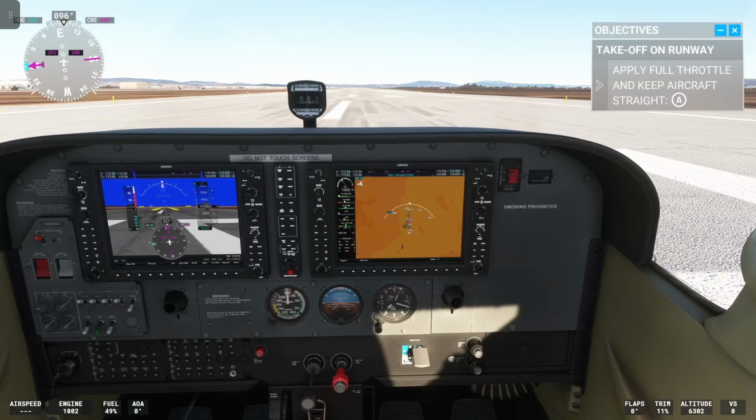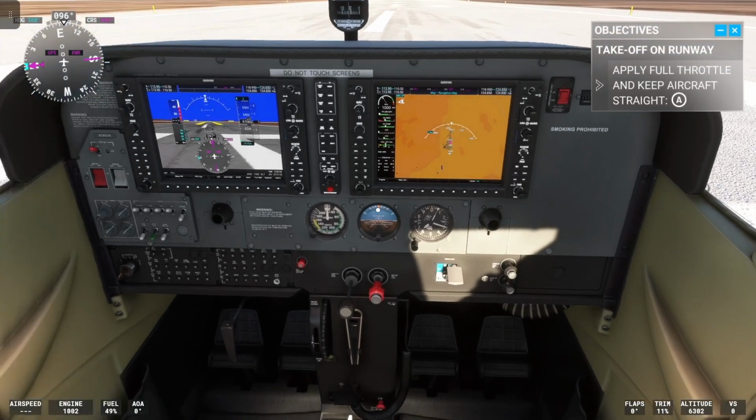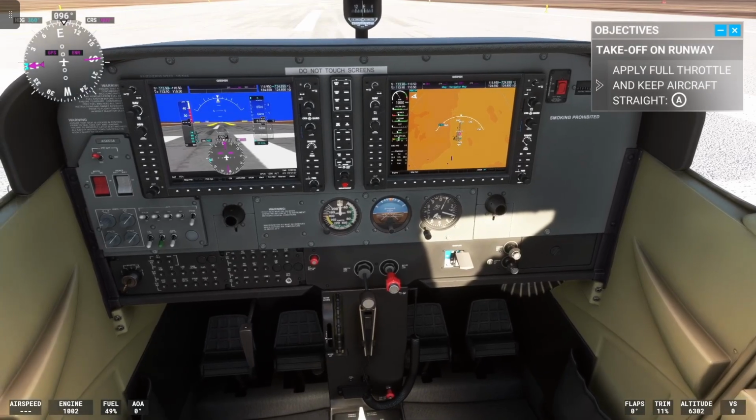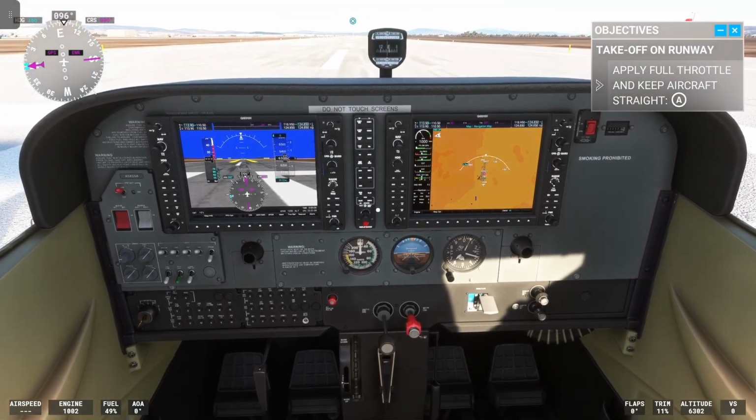You can't just drive up here and do a little U-turn, set yourself up, and take your time. You're off to the side, and you're going to launch like a slingshot, lining up with a runway at a high RPM, a little over 1,000 RPM at least, maybe like a 1,300 minimum, and then full throttle once you're lined up in the middle.